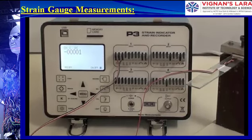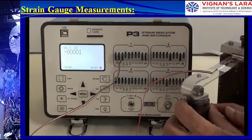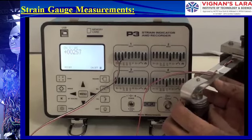The extremely smooth surface of glass makes bonding of gauges to it a challenging exercise. The slight abrasion with 600 grit paper seems to have helped achieve a good bond.